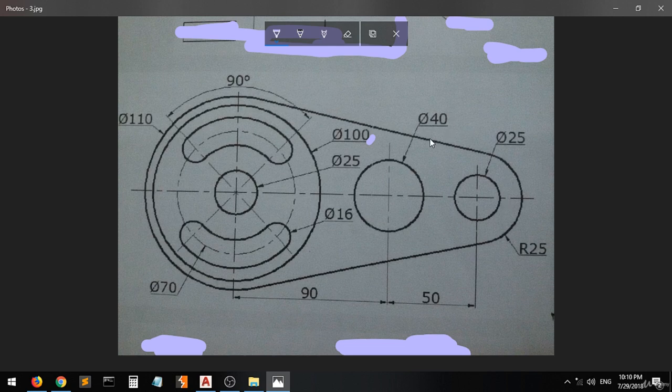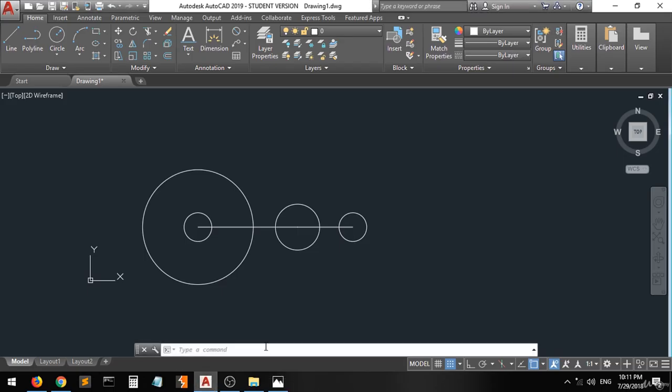As you can see, we have some kind of circle, and it's trimmed from this. It looks like a whole circle, but this part is trimmed. So we'll just draw a circle, the radius of 25, and we'll trim this part, okay? So let's go. Go to the circle from the same center.